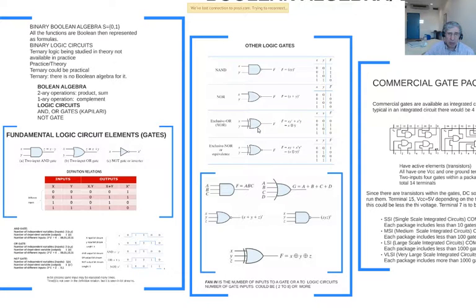Exclusive OR gate. So the definition relation is in here. I can tell you a rule for how to remember this element. If the inputs are different, have different values from each other, let's say 0, 1 or 1, 0, your output is 1. If your inputs have the same value, 0, 0 or 1, 1, your output is 0. So by just looking at the output, you can say what the inputs could be. If the output is 0, that means the input values are the same.